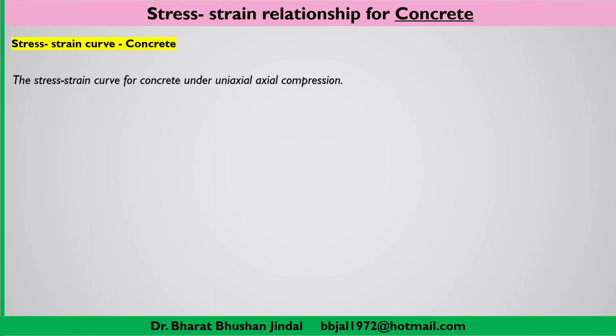Now in most cases we are focusing on concrete structures as a compression member. So the stress-strain curve for concrete under uniaxial compression we will be taking care of, because most of the time we will be working on the compressive strength of concrete when the load is axial compression or uniaxial compression.